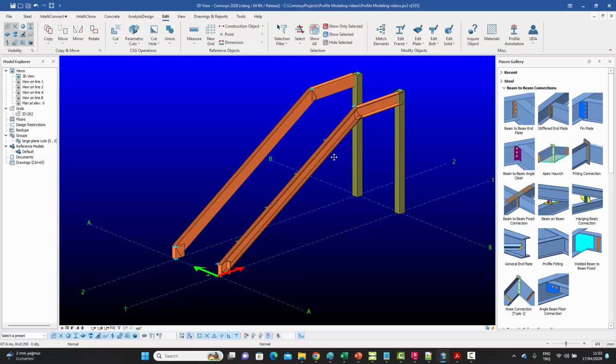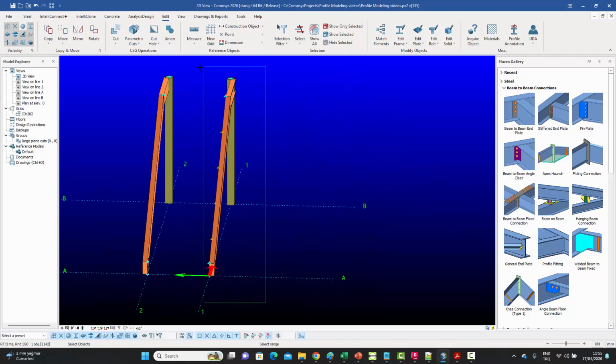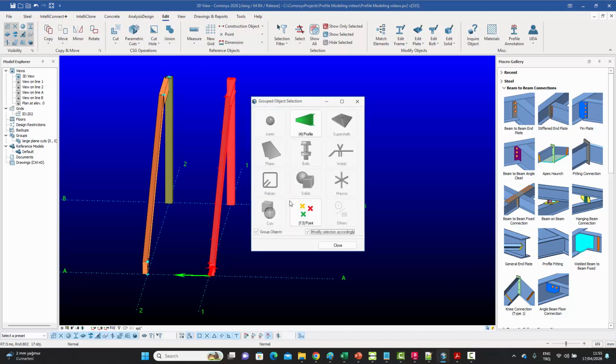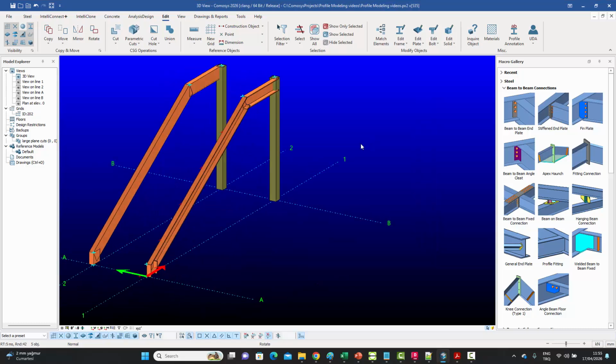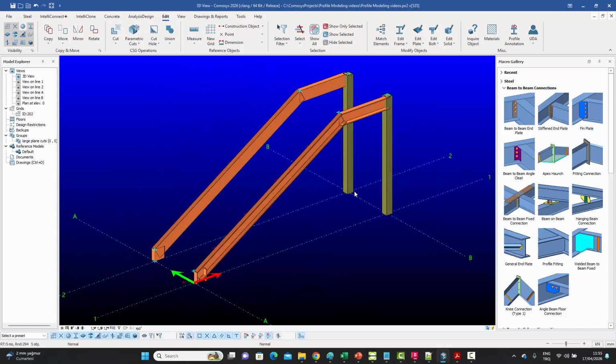on this whole thing. So to center that, what we can do is, well, we can select the points like this as well. We can go like that, press enter. When we click on the points over here, it tells you that you've selected some other points as well, which are the end points of the frames. But those are part related. But the free ones are the ones we just created, the 5 free ones. So we can select those. That would be one way of selecting them.